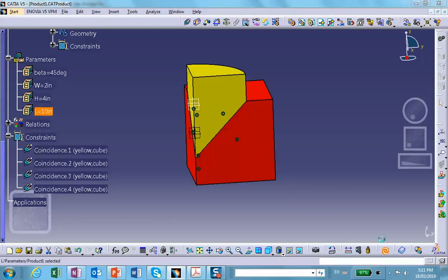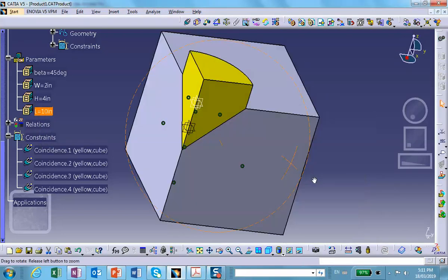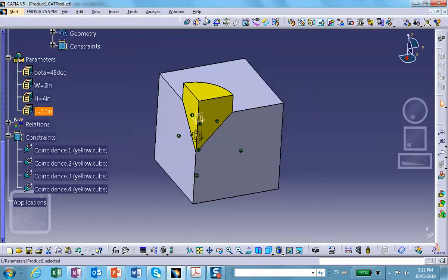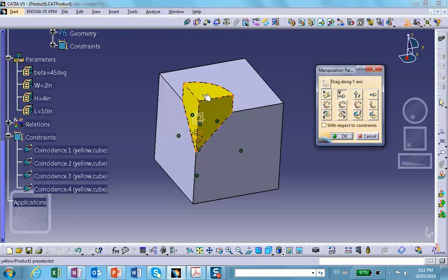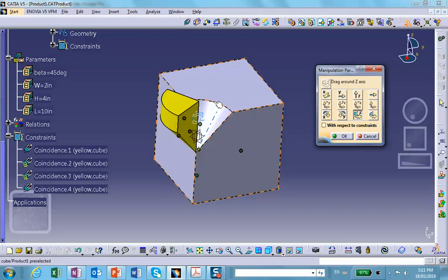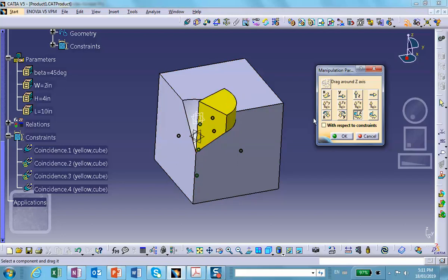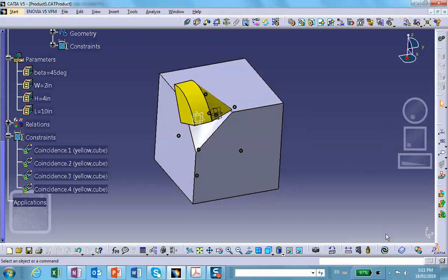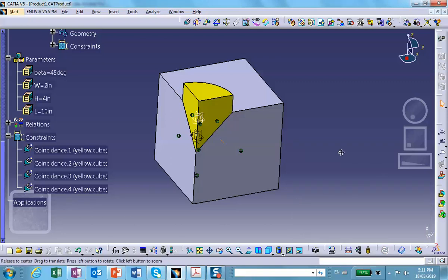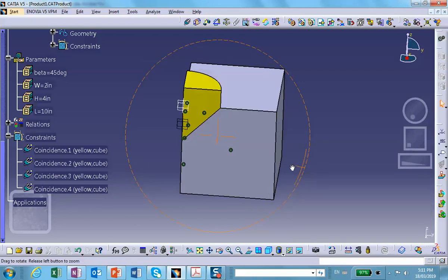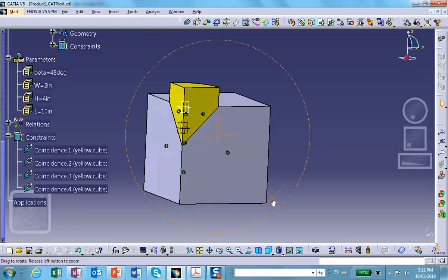And the assembly constraints are all okay. For example, if I did some weird rotation with this and with that, oops, with this, and update, if I put enough assembly constraints, it's going to go back to where it was. So that takes care of this problem without using the copy and paste special, and I'm going to do that thing next. So let me stop.